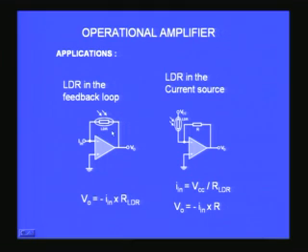There is another way in which the same circuit can be designed. For that what we do is we use the LDR in the current source path. That means you apply a voltage, usually LDRs have got very high resistance in darkness and very low resistance when it is fully bright. So when it is a large resistance along with a large voltage source, you will get reasonably close to an ideal current source.